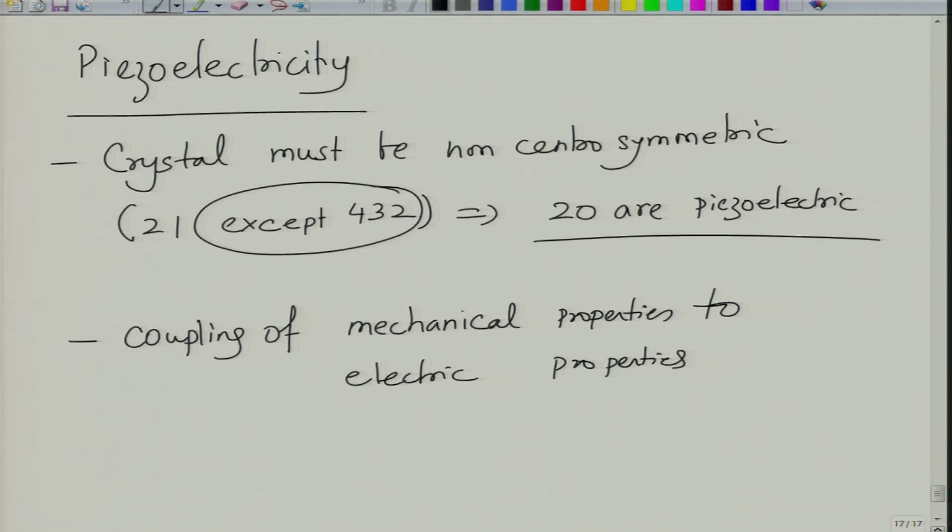So, a piezoelectric material couples mechanical properties to electrical properties. Upon application of a mechanical stimulus, it shows an electrical response, or upon application of an electrical stimulus, it shows a mechanical response. But the fundamental requirement for the material is that it must be non-centrosymmetric, that is, it must lack a center of symmetry. Building upon this further, we get to what we call pyroelectric crystals.